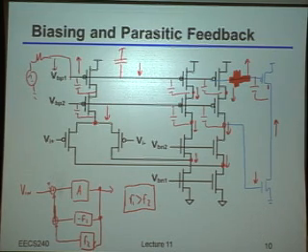But your first solution of indeed just putting a big cap on that bias node there, that's generally a good thing to do. Although we may have to be a little bit careful. You may have to put so big of a cap there that maybe is not always the ideal thing to do. So any other ideas? What else could you potentially do? And let me just redraw the line I got rid of a second ago.